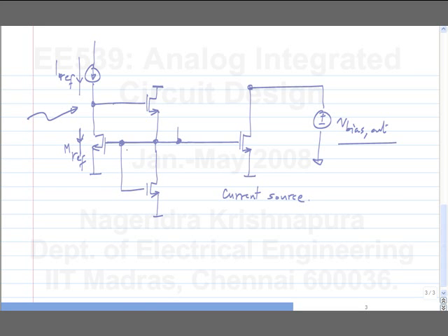I already have the reference voltage available, right? If I ask you to make some current source arbitrarily, what would you do? You would just do this, right? You would make sure that the length of this is the same as the length of this to get reasonable mirroring. So I do the same. I use this current itself to bias our voltage follower. Is this okay or no?